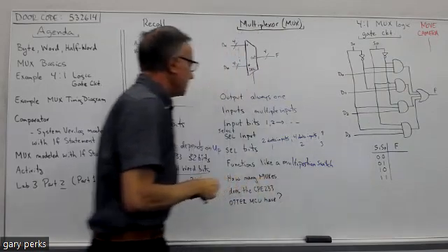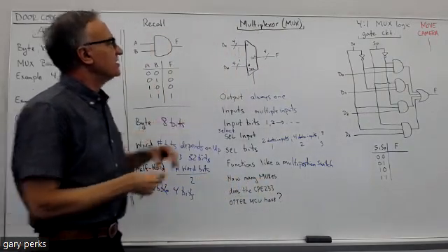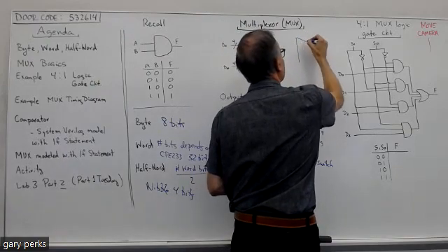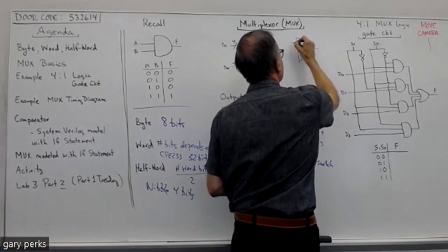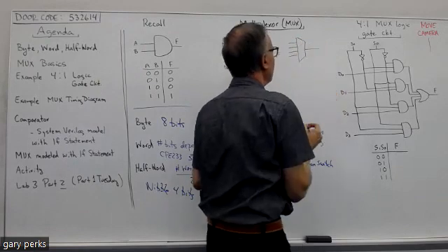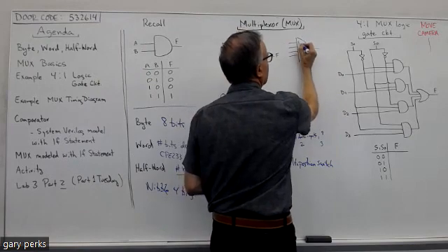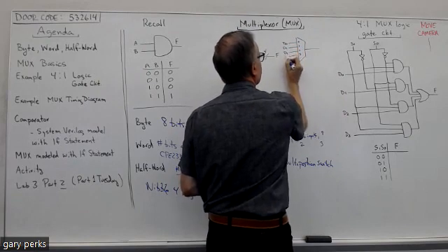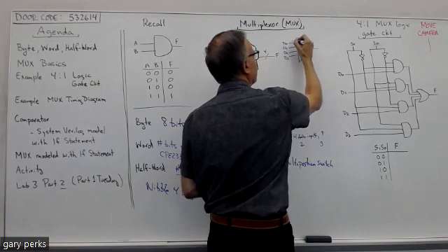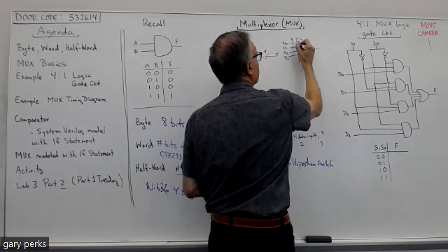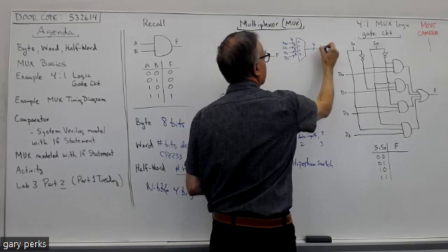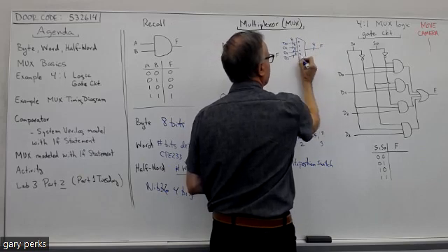Okay, so let's say I had 4 inputs. I'll draw another mux symbol over. I have 4 inputs, and this input I labeled 0, this one 1, this one 2, this one 3. This has data D0, this has data D1, this has data D2, this has data D3. And let's say they're 8-bit data. The output would also be 8-bit. And then I have my select.